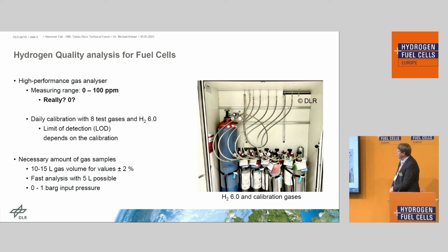And one piece of information: for the necessary amount of gas sample for doing this analysis according to the DIN standard, you need with this system around 10 to 15 liters of gas. And with that you can achieve values with accuracies of plus minus 2%.